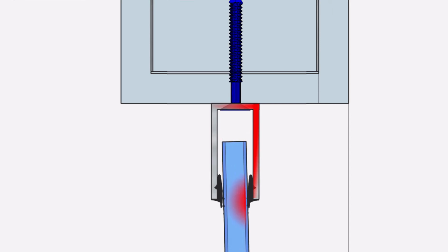As the glass deflects, it gets pulled out of the top channel. If you install glass and the rubber falls out of the top, it could be a result of deflection. And depending on how much glass bite you have at the top, perhaps an insufficient glass bite and excessive deflection, you end up with loose gaskets.